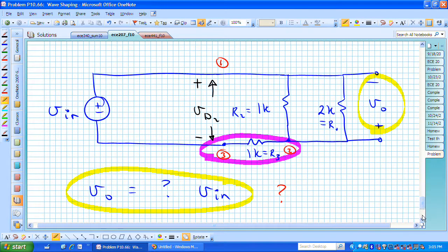So how do we solve this circuit? Well, we could do some KVL equations, and then we would have, I see, two loops, if we wanted to. Or, excuse me, what I'm seeing we could also do is combine the R sub 2 and the R sub 1 into a parallel combination, and then just have one loop, and the voltage dropped across the parallel combination of R1 and R2 is V naught, or the negative V naught, and we could then just do our analysis that way.